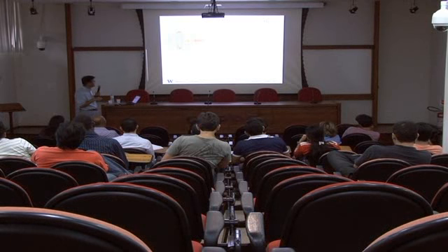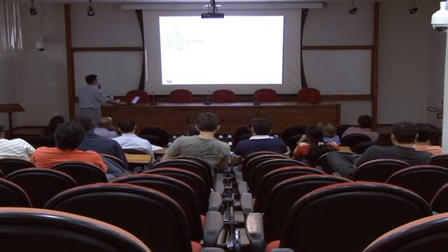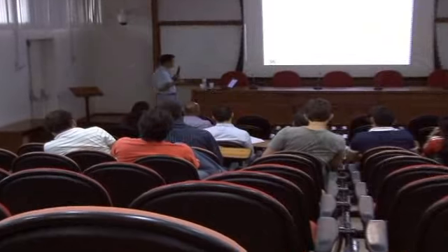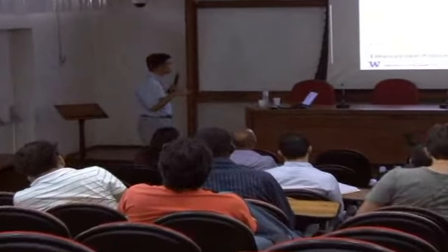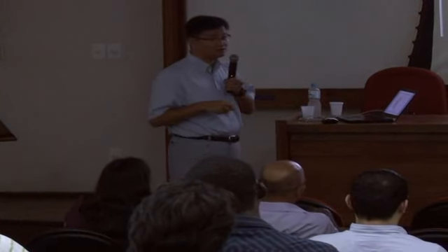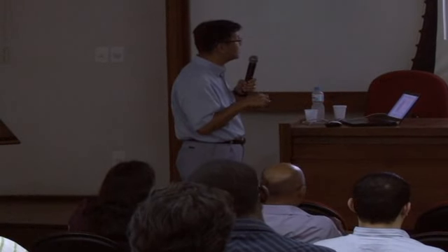And then we have a constant with the gradient of electric field. So the main contribution of this nanotip is to increase the field strength. Then that will proportionally increase the force to attract and concentrate particles. And this graph shows scaling issues. So particle size is from 1 nanometer and then 10 nanometer, 100 nanometer, and then 1 micron, 10 micron. So our target is within this range.